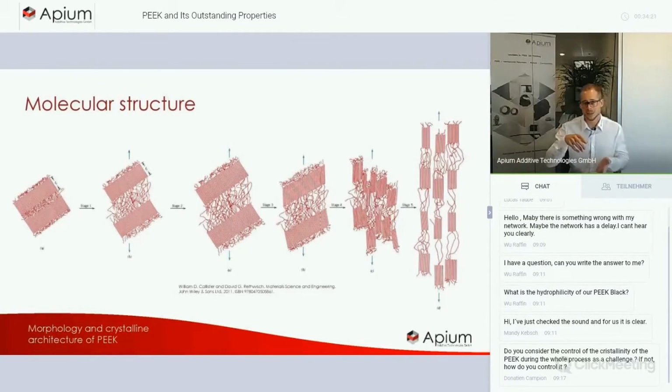This can be either in the elastic way, or then if we disentangle more and more, it will be in the plastic way. And then the crystalline parts come into play when the polymer chains in the amorphous regions cannot be stretched anymore. The crystals start to slightly shift according to Schmid's law, but I think this is too deep into the material science.